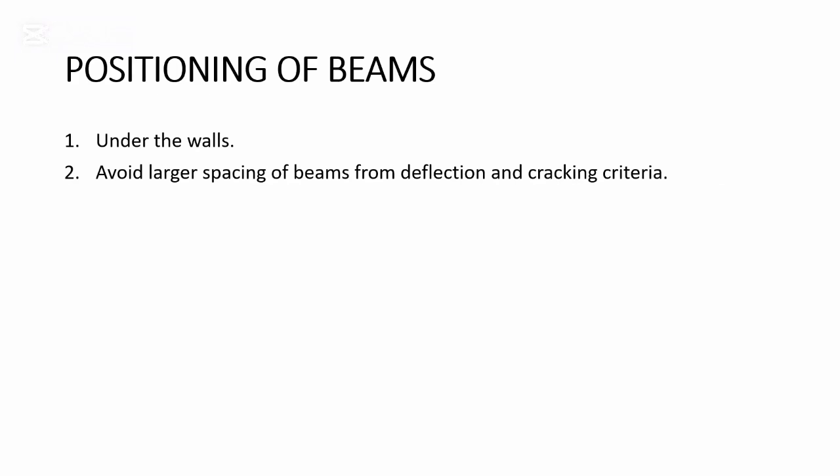Now, coming to the positioning of beams, it is really simple. That is, I should place my beams under the walls, and I should avoid large spacing of beams from the deflection and cracking criteria.